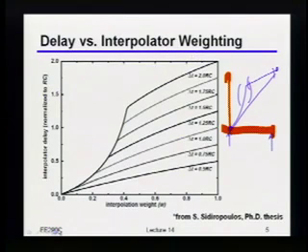So intuitively, this is really telling you what we said earlier. What we basically said was, look, we want that delta t to be very closely related to the edge rate, right? Because if we make that delta t too large compared to the edge rate, which is these curves up over here, that's where we're going to get these nasty step-looking behaviors, okay? So in other words, we can now say something much more quantitative.